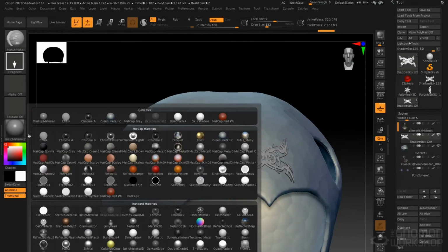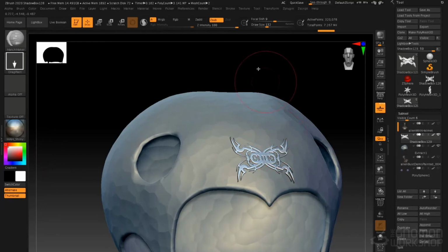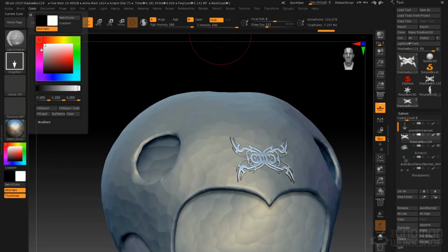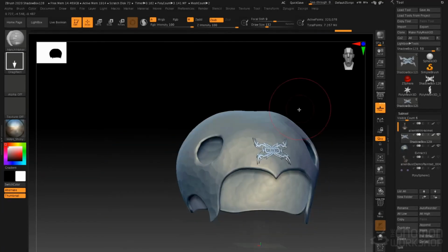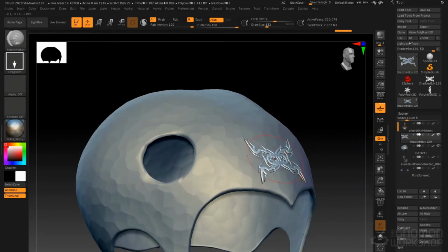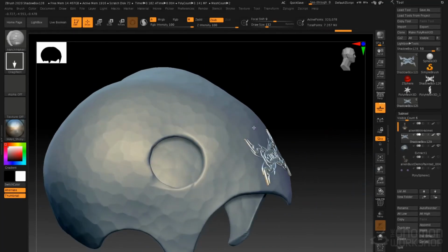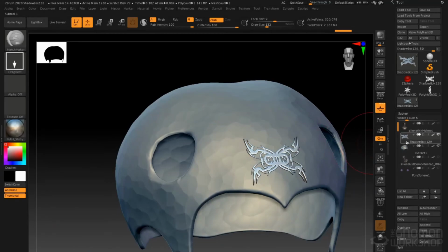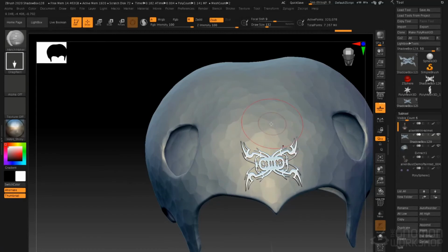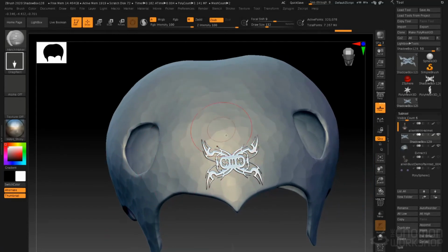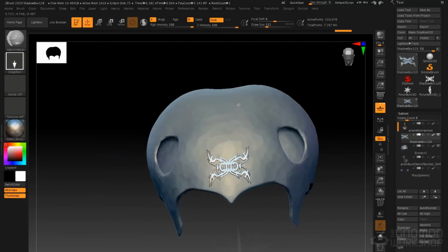Now let's go ahead and change the material on this. Let's give it a shiny material. Go to Material, Color, Fill Object. Now any object can be match made into the object beneath it. All you do is just place it, orient it so it's looking down the projection angle, and then use your matchmaker brush to click and drag, letting go off the surface. And that should conform that to whatever shape is underneath it.